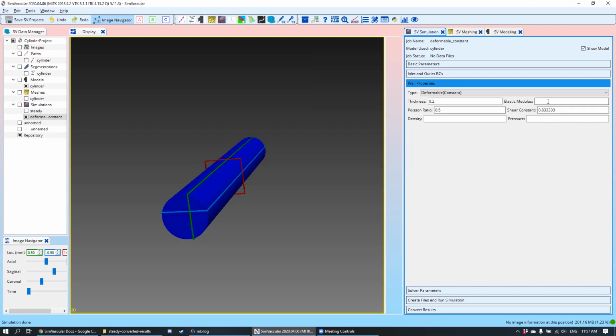These are difficult because there are very limited measurements. You might find some cadaver measurements out there, but those aren't going to be totally reliable. So here you're going to have to make some assumptions. You might have to cross-reference between a few different literature sources. In this case, I'm going to use an elastic modulus of 0.4 megapascal.